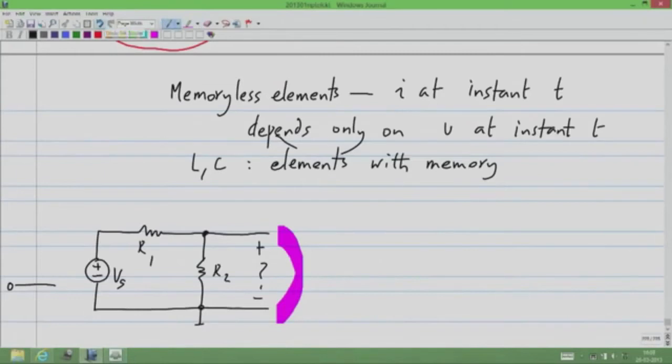So this voltage clearly from the voltage divider formula is Vs times R2 by R1 plus R2. Okay, and if Vs is 0, this voltage is also 0. Okay, this is a simple resistive divider. Now let's say it jumps from 0 to some voltage Vp. Okay, what happens then?